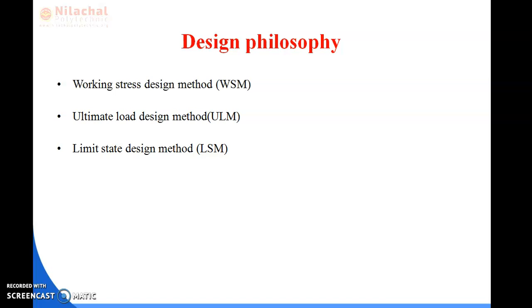So we prefer the limit state design method, which is suitable for serviceability as well as strength of a structure. In steel design, all members like compression members and tension members are designed by the limit state design method, which can give good strength and good serviceability.